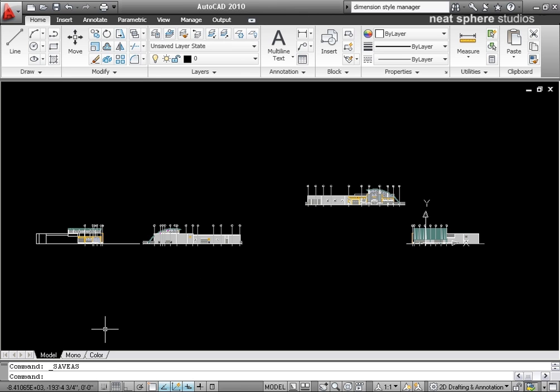So looking at what we've got at the bottom of our screen here, we still have the very traditional command panel, which I would urge you to keep open rather than minimizing down, simply because it does allow you to, should you wish to type in a command, if you've used previous versions before, you can do so from there. But also there will be certain amounts of data that you will work with, such as the area of a shape or the area of a room or the volume of a space that you may well wish to inquire about later on in the program as you work through your examples. And you'll find that it's actually very easy to just come down here to the command panel and copy and paste that into, say, a table, for example. So I like to keep that available for me at all times.